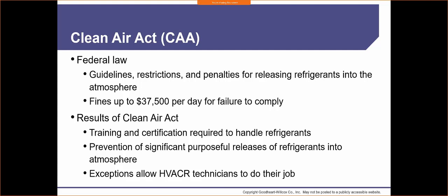All right. There are exceptions that allow technicians to do their job. Like I said, we're going to release tidbits of refrigerant up into the atmosphere. It's just part of doing it. There's just no other way. But we're trying to capture as much of it as we can. The other thing too is when you're working on refrigerants, your hoses have to have some type of safety device on there to hold the refrigerant inside the line.